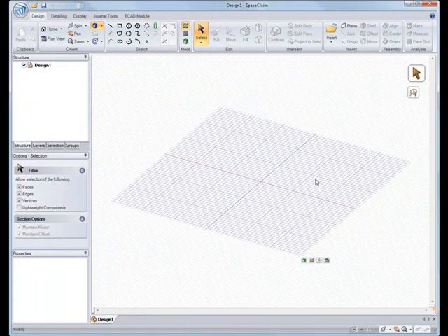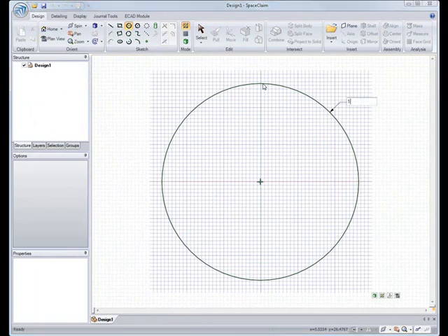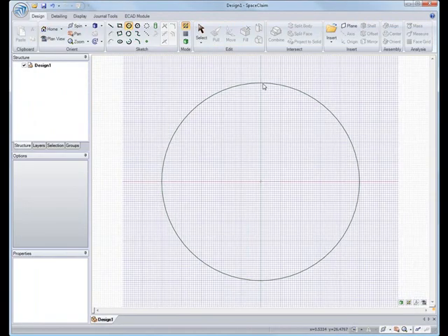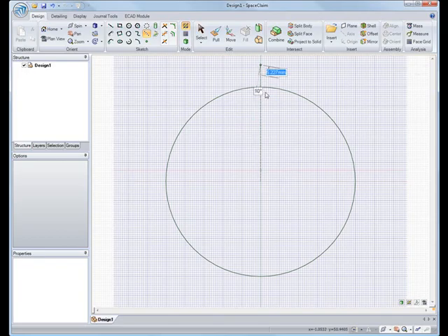Here we're going to be talking about involutes and how you can create them. You're probably more commonly used to them as being the teeth on a gear. So we'll start by making our base circle. And now we want to sketch the profile, but we're going to need to have some construction lines. So I'm going to create a line from the center every 5 degrees to help me start to make the involutes.